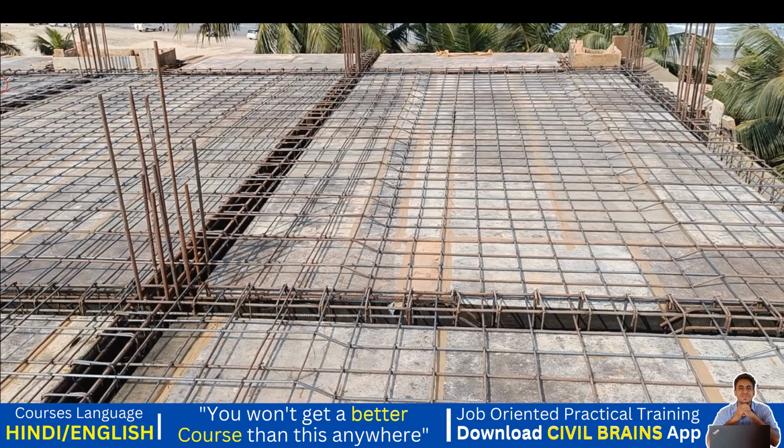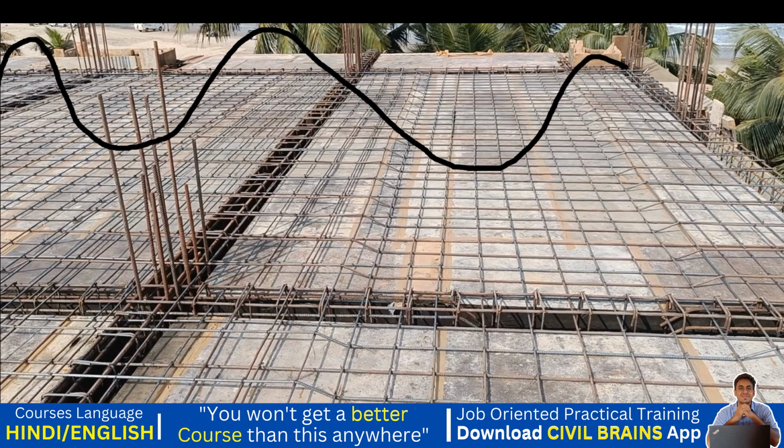I'll start with this. Here I'll get a negative bending moment, then a positive bending moment, then a huge negative bending moment here, a positive bending moment, and again a negative bending moment. If I try to put one straight line to differentiate that, let us say this is my one straight line, right? Whatever is above the straight line, that is this part and this part, is a negative bending moment.